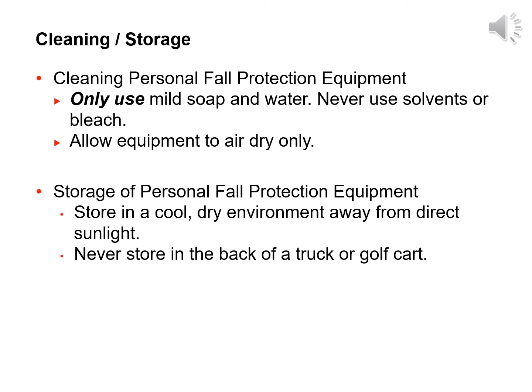When you are done with your equipment and need to put it up, be sure to store your equipment in a cool, dry environment, away from sunlight. The UV rays in the sunlight can harm the material on the fall protection equipment. Never leave your fall protection equipment in the back of a truck or golf cart. Weather will make the equipment become dry and brittle.